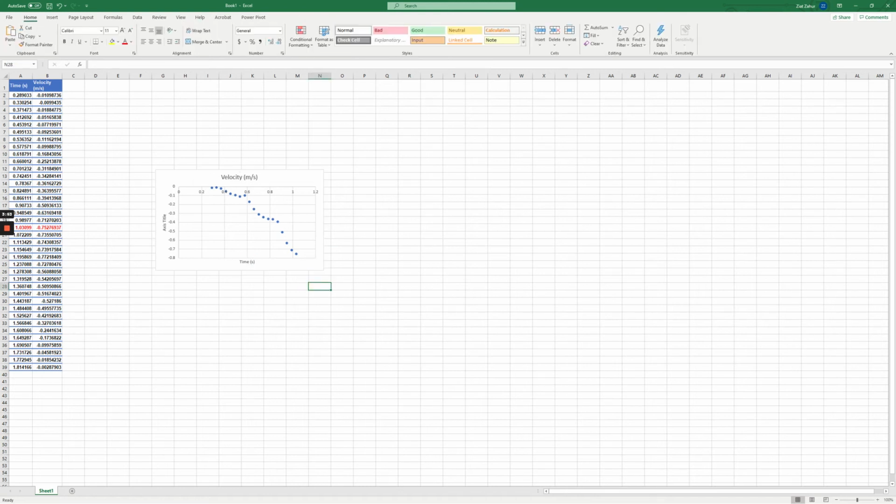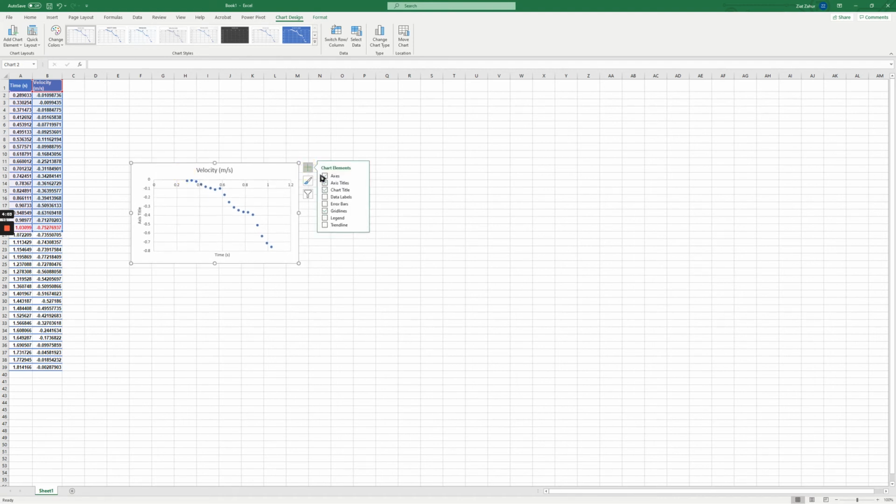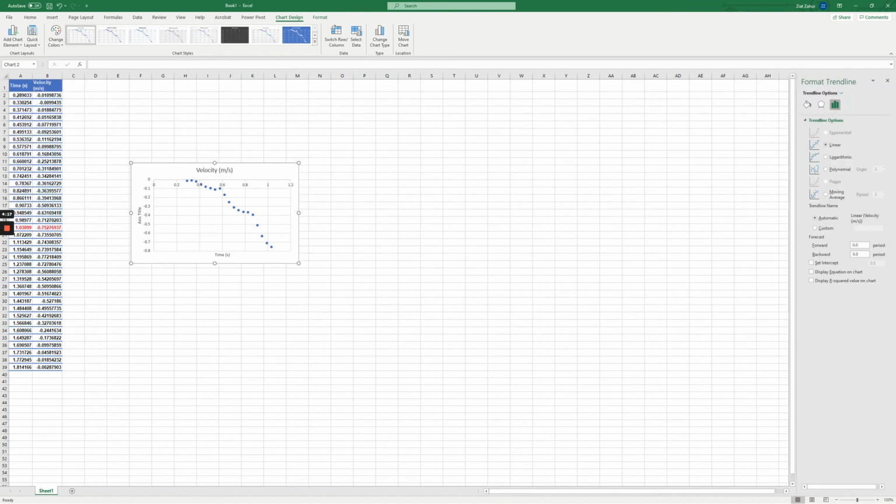But more importantly, what we would like to do is model the function based on our data. Typically, when your sensors just give you raw data like this, you can insert a trend line. Now, the linear trend line is the default function, so it will just draw a trend line here. But instead, what we want to do is go to more options by clicking on the green arrow, and this will allow us to show the equation on screen.